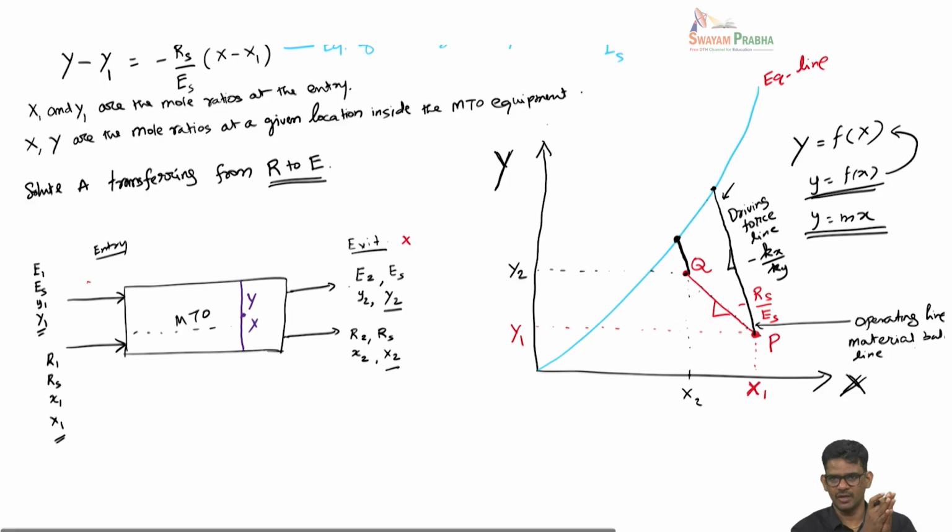So when you enter in co-current flow, at the beginning there is a larger driving force for mass transfer. As you go slowly inside, the driving force diminishes. When you come outside, at the exit point, the driving force would be something like this. That's a characteristic of co-current flow and the corresponding mass transfer.